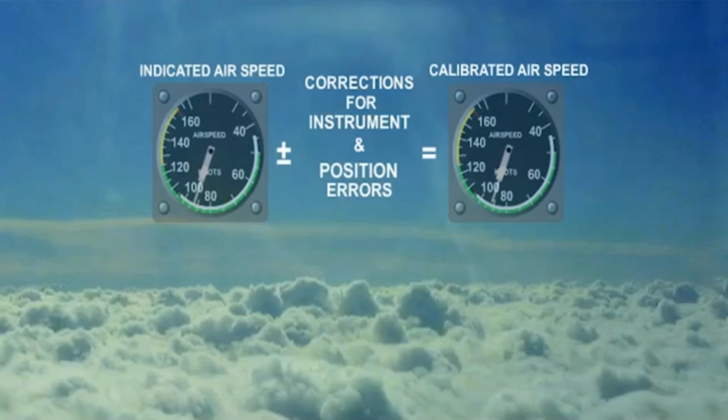To summarize then, the indicated airspeed, plus or minus instrument error correction, and position error correction equals the calibrated airspeed.